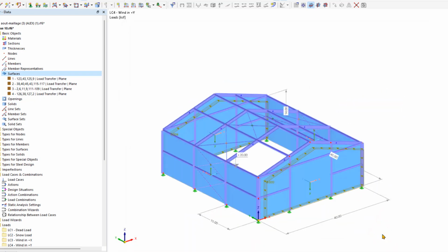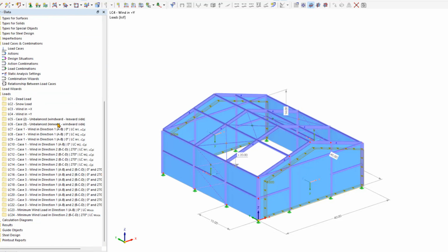In our example, we've entered the wind loads for the roof and the sides of the steel hull in separate load cases. These loads act together from the same directions. We've also assumed that we cannot automatically generate these wind loads on the vertical walls using the load wizard. To consider this interaction, we select the lateral wind loads in the navigator and add them by right-clicking on the respective automatically generated wind loads of the roof.